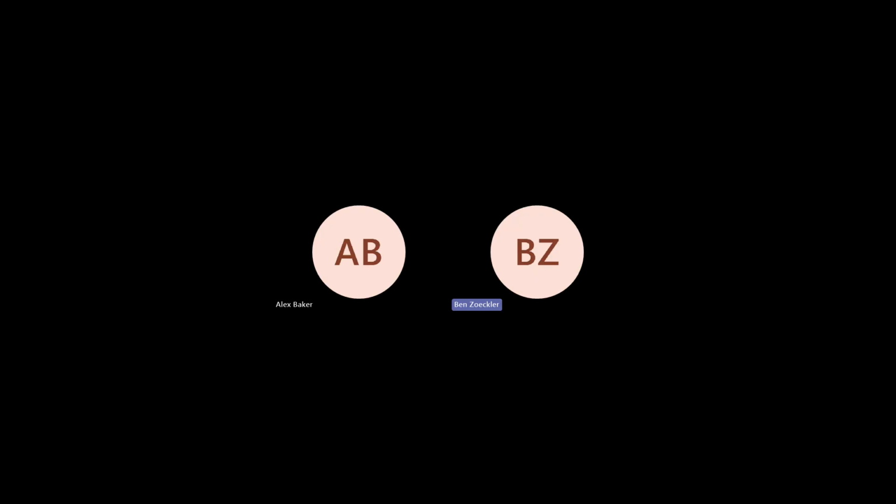I have to dig deeper into it. Whenever I click on show the mold base, click on cooling and then temperature, for some reason it just shows it projected on the part, doesn't show it projected on the mold base. Yeah, my error. Make sure you go over to the model tree, the second tab here, and you'll have to turn on your mold base.